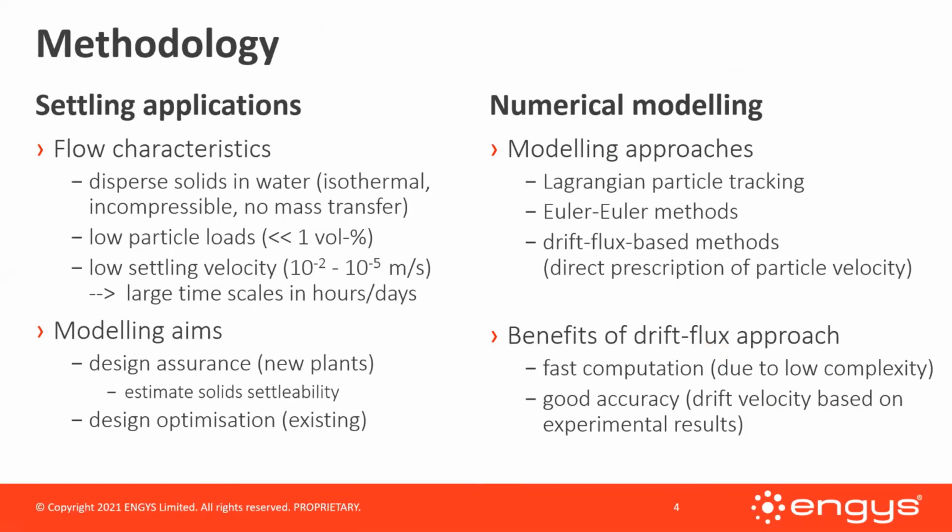Now let us get to the methodology employed in the numerical simulation of settling applications. The flow characteristics are dispersed flows in water at low particle loads and low settling velocities. The modeling aims at design, assurance and optimization, and in general, the main aim is to assess solid settleability. Available numerical methods for this type of applications are naturally Lagrangian particle tracking and Euler-Euler methods.